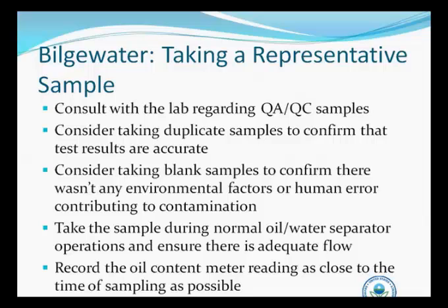So the other things you'll want to do while you're sampling is also consider taking the sample during normal operations of your oil water separator and ensuring that there's adequate flow. So you don't want to take one sample one day, realize there's not enough flow, and have to take it another day. And then immediately after taking that sample, you'll want to take your oil content meter readings as well.